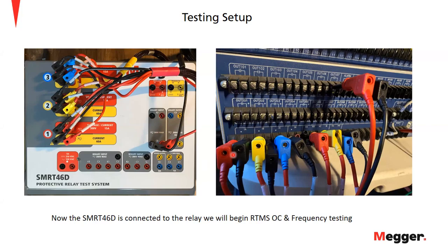And this side, we also have our relay, which is the back, and how I have this wired. A phase again for our currents here. We'll match B phase currents as I have here, and then also C phase current here. And then the voltages follow right behind it, right? So the same color voltages, red for A phase, yellow for B phase, and blue for C phase. And then we have our return for our neutral on our voltage as well.